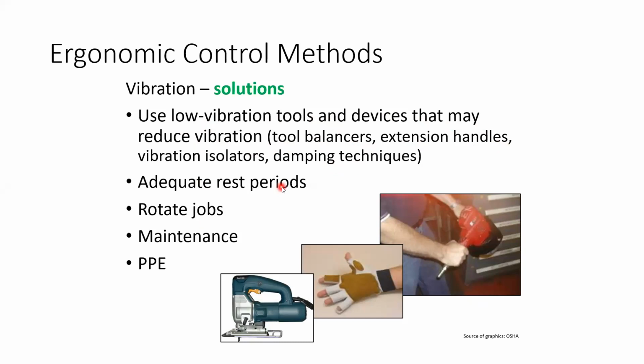Educate and give rest periods. Rotate jobs, so it is not only one driver. Do very good maintenance, and use PPE. Okay, this is the solution for vibration.